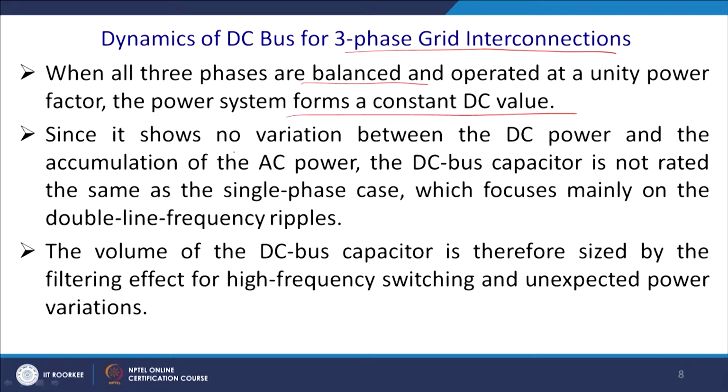Since it shows no variation between the DC power and the accumulations of the AC power, the DC bus capacitor is not rated the same as the single phase case, which focuses mainly on the double frequency ripple. That is something quite important in case of the 3 phase system.